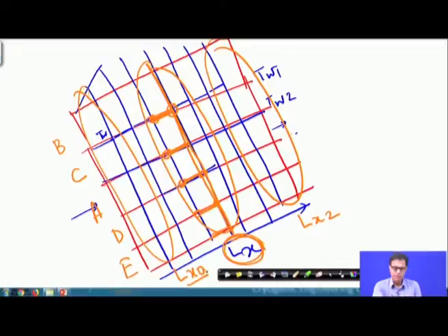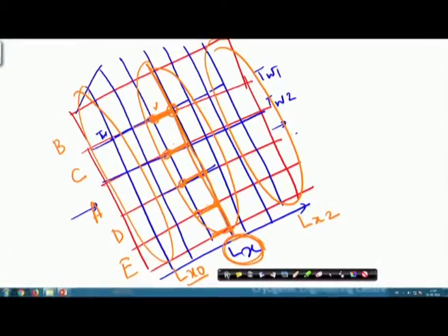So, we try to find out the wall temperature at a particular cross section of the heat exchanger, and if we find that they are more or less uniform, then we say that the stacking pattern is an optimum stacking pattern. Or we can say otherwise that an optimum stacking pattern will follow this kind of temperature profile along the length of the heat exchanger at a particular cross section.